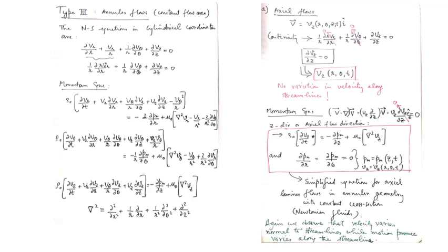Okay, and the Laplacian operator is already written on the bottom left, so you can just apply it to Vz with the fact that ∂²Vz/∂z² will be 0. So when we apply the Laplacian on Vz, we will set the second derivative with respect to z to 0, because Vz is not a function of z, already concluded from the continuity equation.